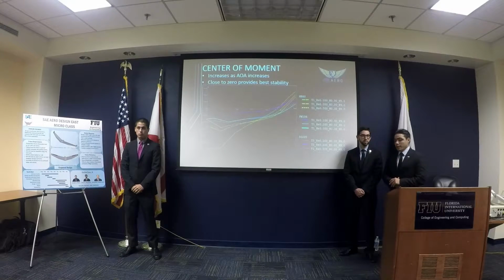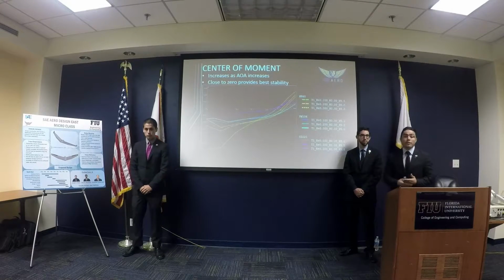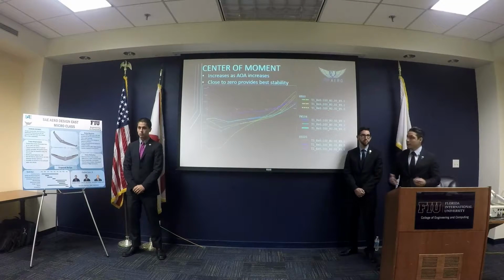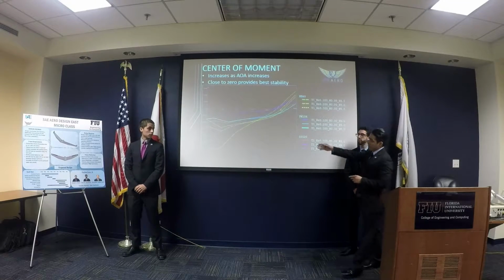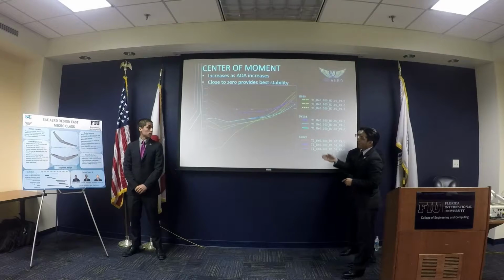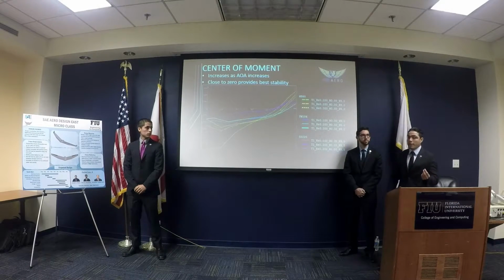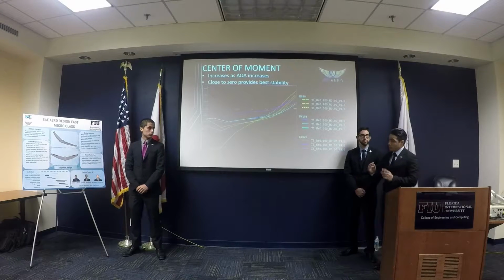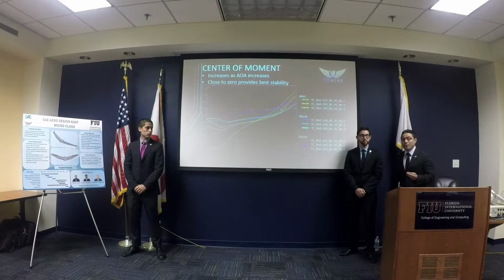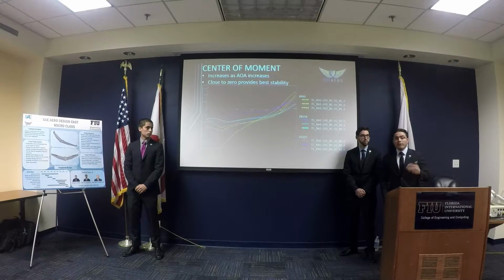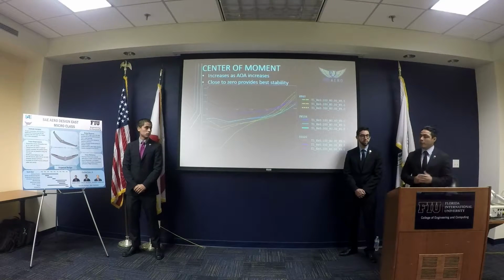The center of moment for our design is very important. As we're going with a flying wing design, we don't have a vertical stabilizer. Therefore, as you can see here on the y-axis of this graph, the center of moment is relative to the center of gravity of the aircraft as well, as we want to achieve the center of moment to be as close to zero as possible. Therefore, we're choosing airfoils that are going to give us those characteristics.